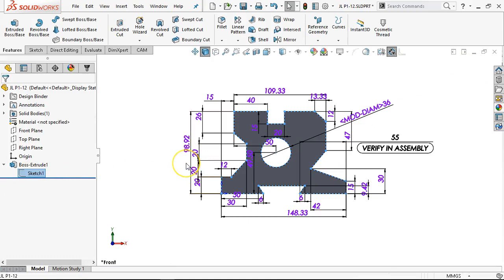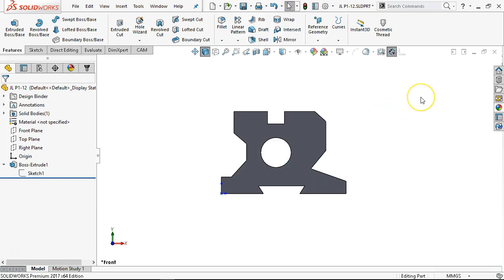So in this case, we're just kind of concerned with this one, I would say double clicking and getting all of those dimensions up without going back into the sketch, even though I would have to hit the rebuild or the Control B or the Control Q. You know, again, way too many options. I'd rather tell you just always hit Control B or always hit the little stoplight up here when you're telling it to rebuild.